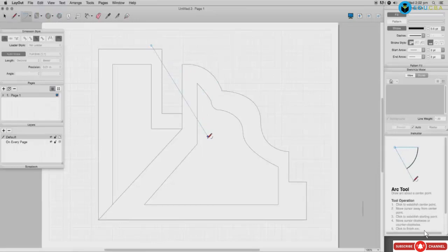The next tool is arc. You can create an arc very easily without going through making a circle and dividing the circle. You can straight away create an arc at a predefined angle. You can go on connecting the arcs also to have a complete diagram.